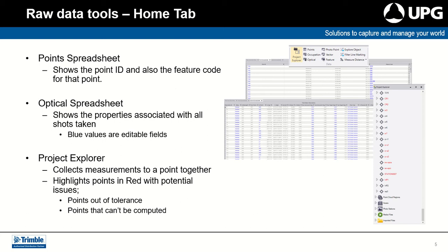When you're out in the field and you delete a point on an access controller, that point will still be stored, however it will be stored as a disabled point. So this is why we say we do retain that data integrity. You still have that record of that point. In here, if you're having an off day, you can also edit the total station height or the target height. And you can also change the prism type to edit the prism constant if needed. We let you change these parameters as you need because we know that sometimes there needs to be edits.